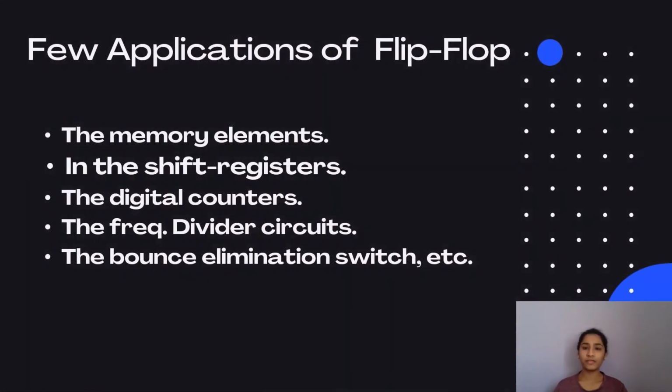Now when I talk about flip-flop, a flip-flop is nothing but a bistable device, which means that it has two stable states and it can store one bit of information. As flip-flops are used to store information or data, they are used in memory elements, shift registers, counters, frequency dividers, and bounce elimination switches.